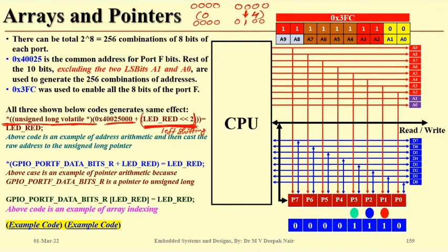Rather, if you are interested to bring one in the third place from the left, you can use this kind of command with whichever register it is, and just use this particular left shift by 3. What does that mean? First place, second place, third place, automatically in the third place you will have 1. Okay, so this will help you.